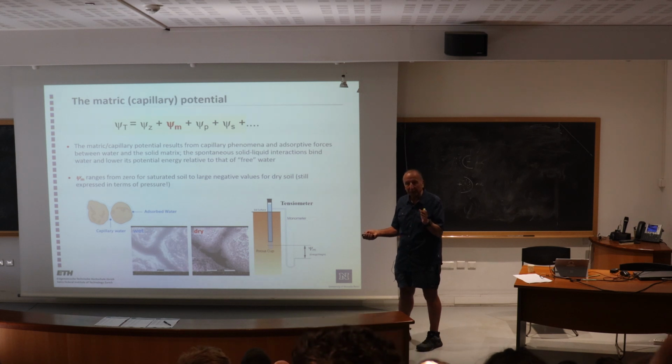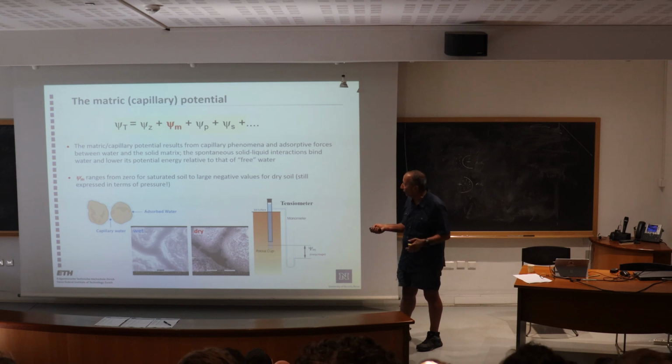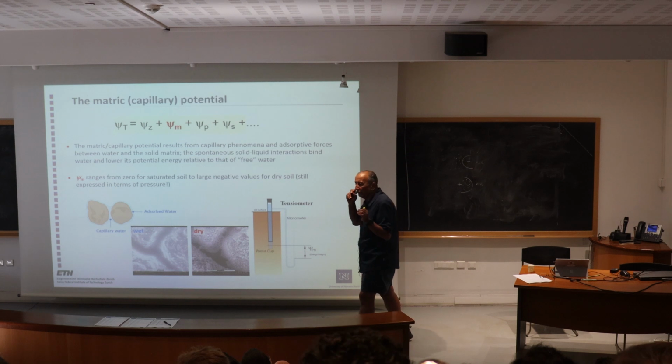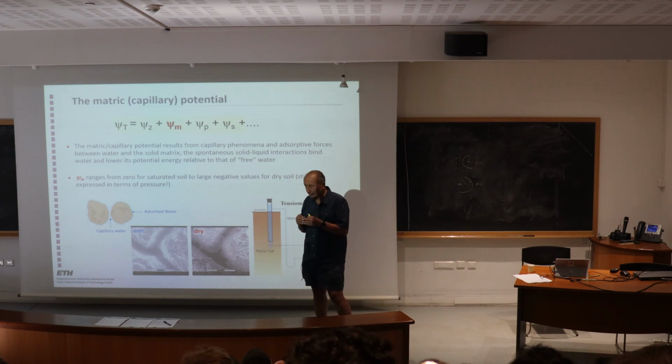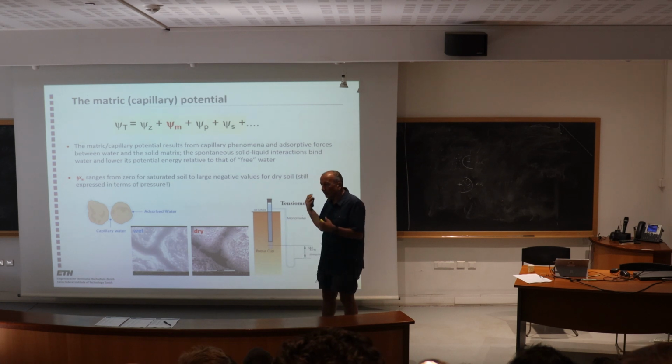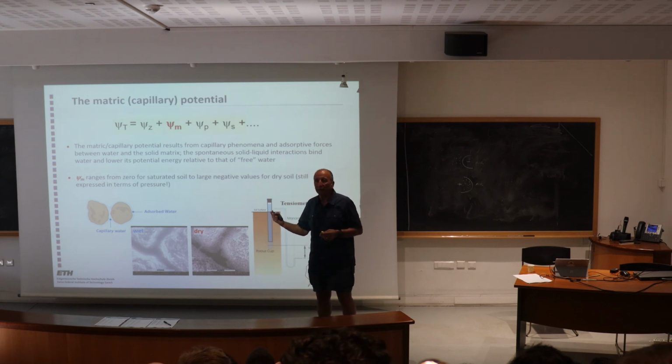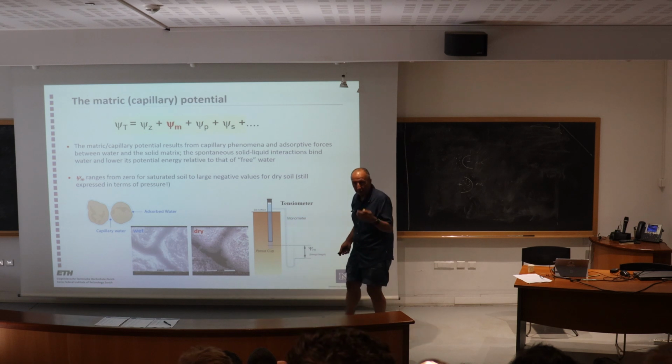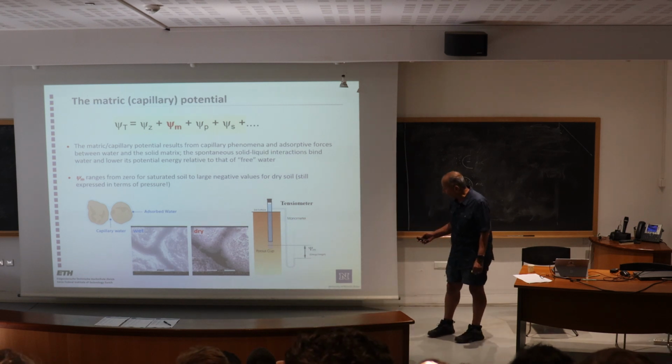mostly focus on that. But also there is a component of adsorption, that is liquid-solid interactions, but we typically don't tend to focus on, and I'll try and highlight it in today's talk. So remember, when I talk about matric potential, we lump these two together because we don't have a way to separate this, to measure this independently, but we recognize that these are really two independent components, and sometimes, especially when the soil is dry, one will dominate over the other. You can imagine that, just visualizing how water is held in soil.